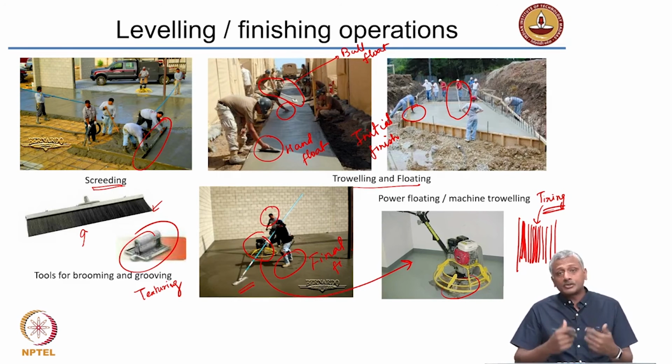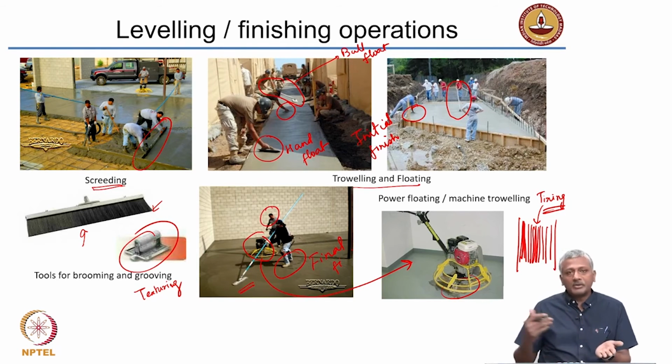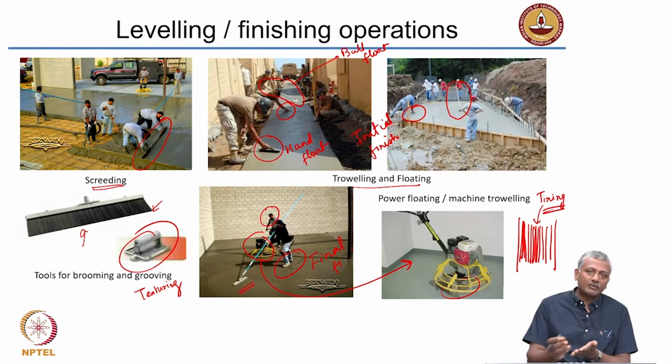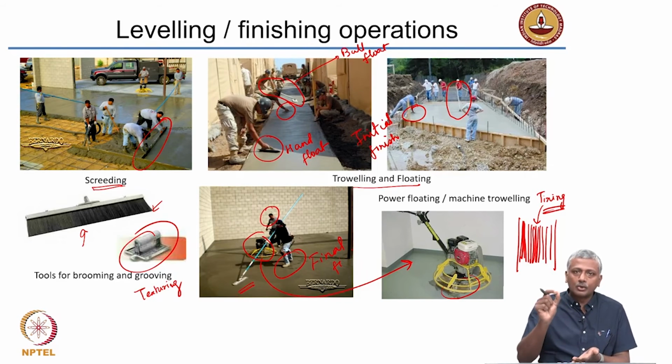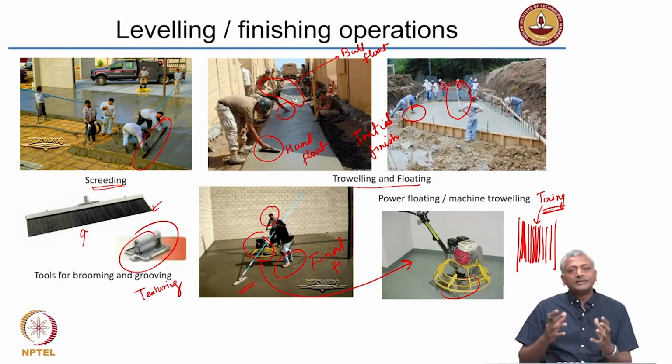And this also reduces the tire pavement interaction noise. You may have seen that on highways, a lot of noise is generated when the vehicles move on the surface. When you provide these air pockets or grooves on the road surface, they absorb a lot of this noise and reduce the amount of noise that gets generated from highways.